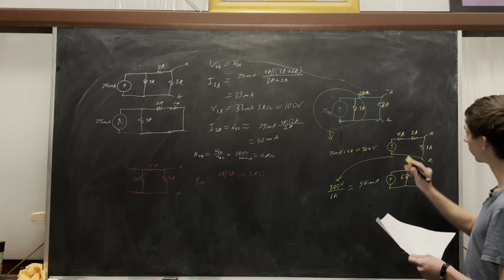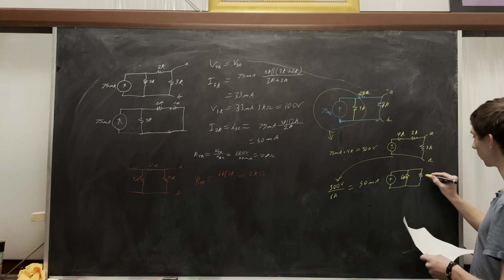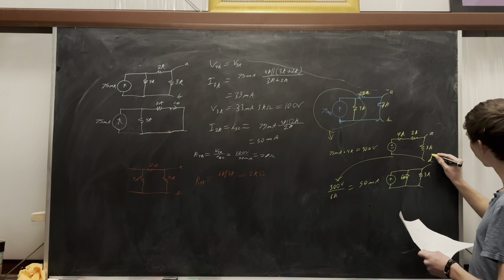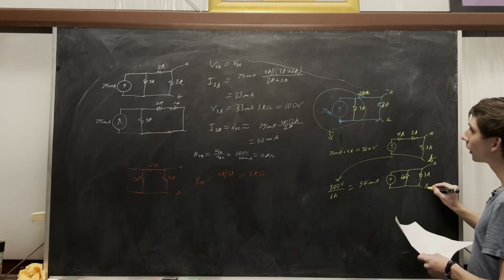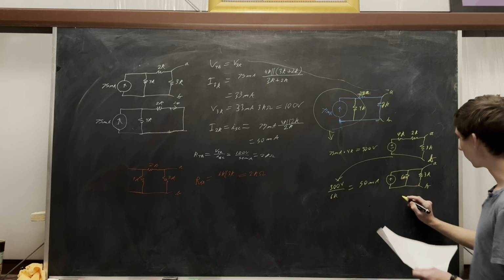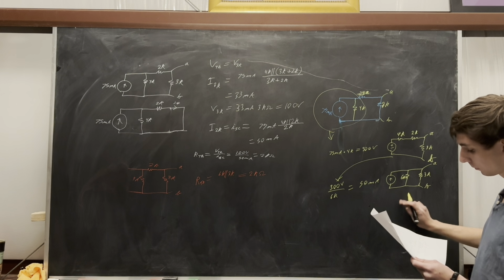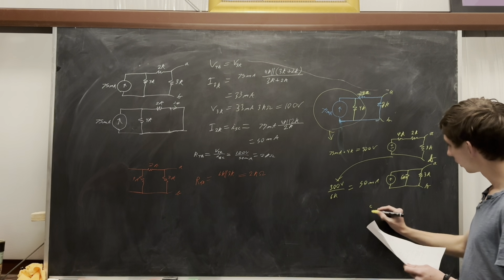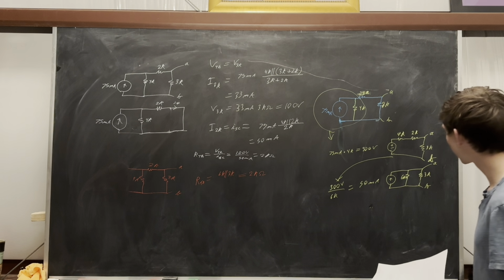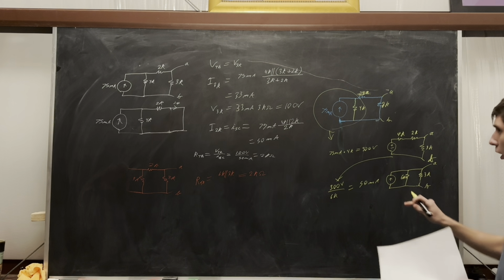And here we'd have a series combination of these two, so 6 kilo ohms in parallel with 3 kilo ohms. You can combine these two in series and do another source transformation. So we already know from this 6K in parallel with 3K is 2K. So if you wanted to just redraw that with just a 2K here, we'd have the Norton equivalent.